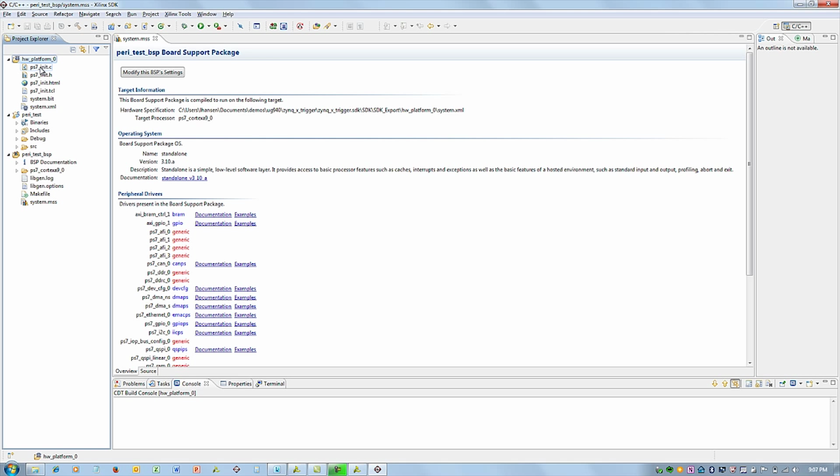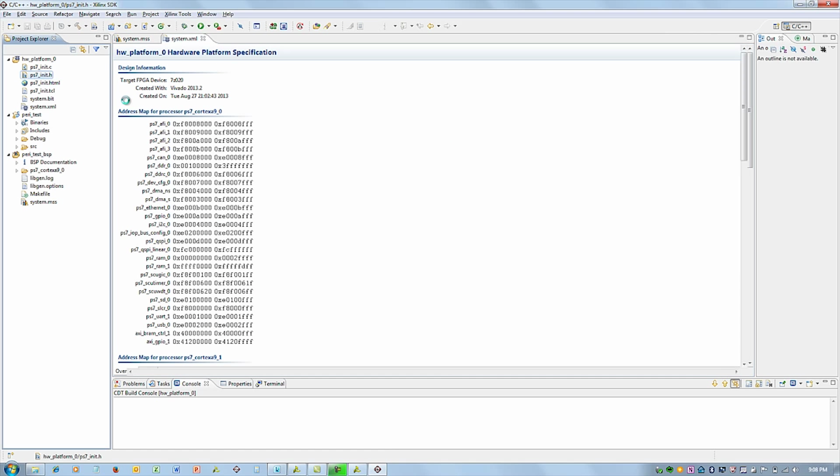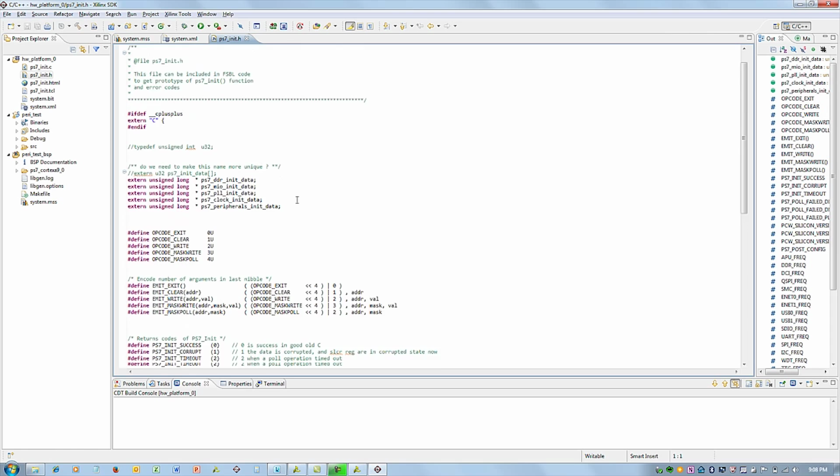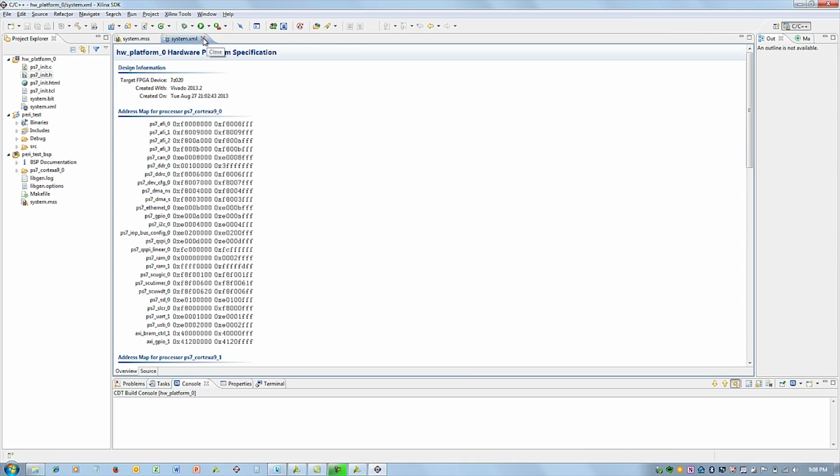So these two tools, Vivado and SDK, can be run in parallel. In fact, you can download free versions of standalone SDK for your application coders that will never get near a hardware design. Notice I'm looking at my system XML file. This is all my hardware description, everything I need to initialize the Xilinx processing system. All those files have been written out, they're correct by design and ready for me to start.